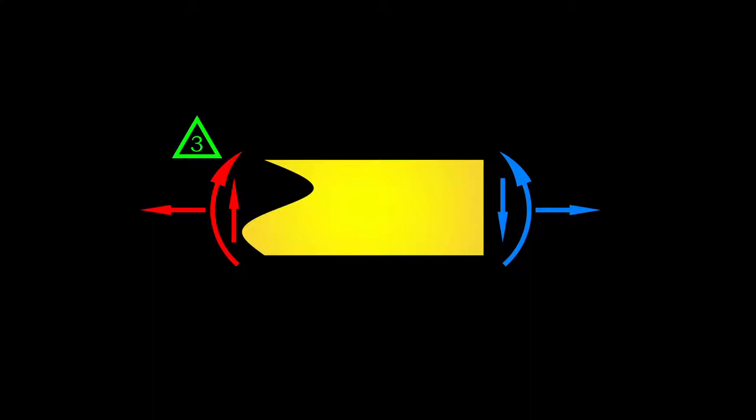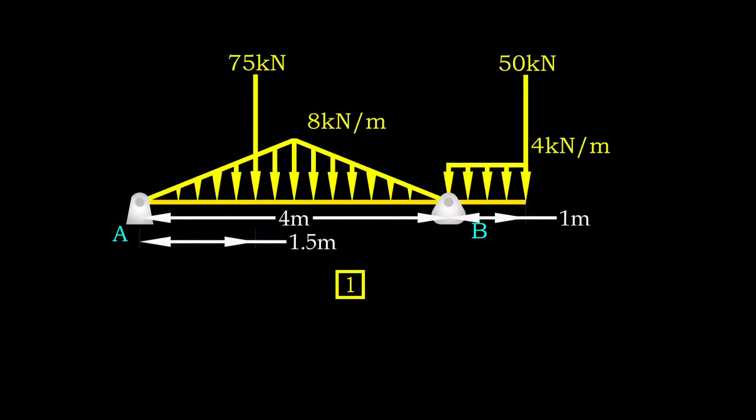We know axial force, shear force, and bending moment may develop in a loaded beam. To hold the beam in place, equilibrium must be achieved in x and y directions and moment about any point. Therefore, at least 3 support reactions are needed for every member. For this situation, we have only one beam. 3 reaction forces must be provided by support to make sure the structure is stable.